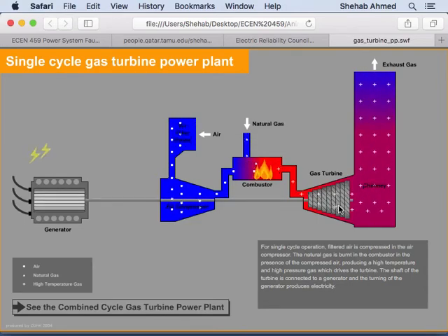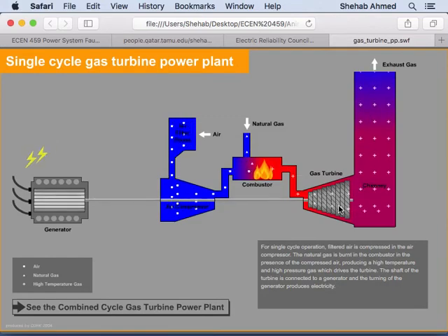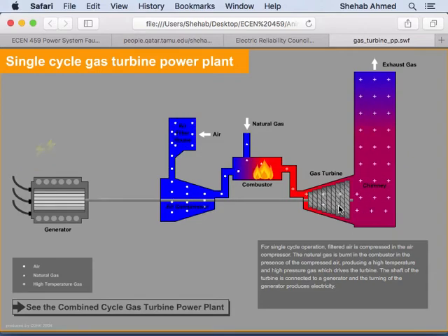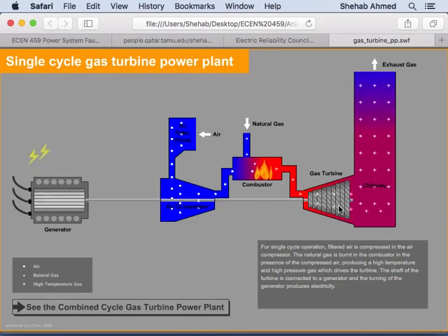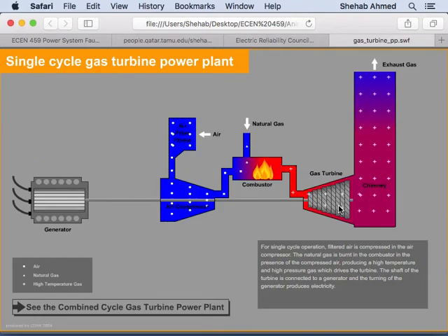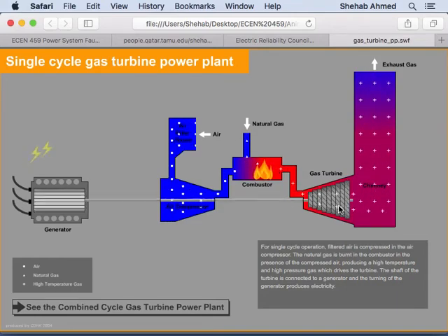They're called peaking power stations. We have 2 or 3 of those around Doha, and what they do is provide the flexibility, right? These are gas turbines, they're on demand. You can increase the amount of gas coming in and produce more load instantaneously, very quickly, right? So you're not generating steam, you're combusting natural gas, right?